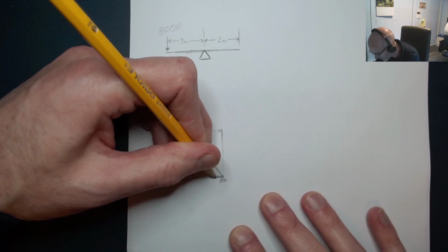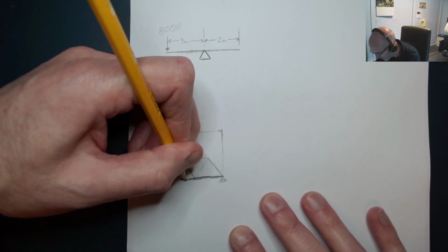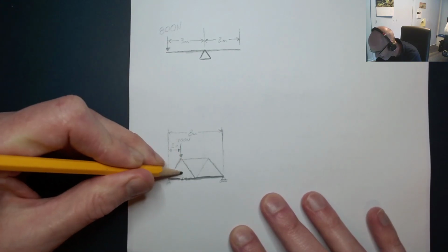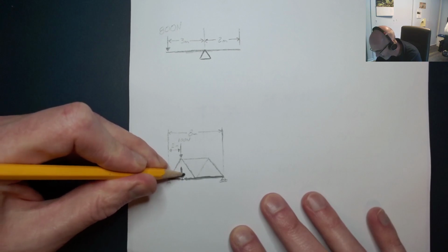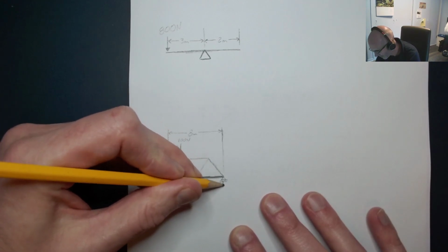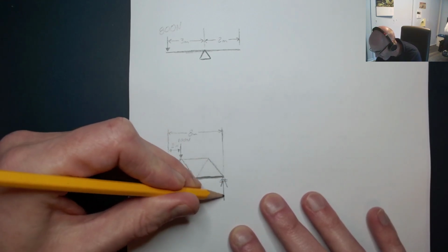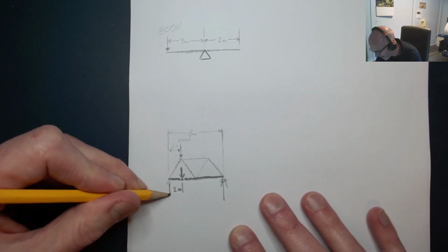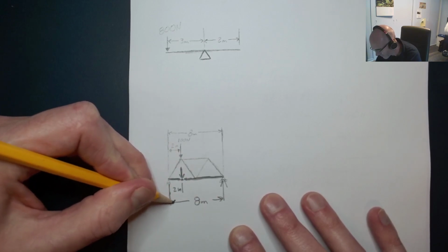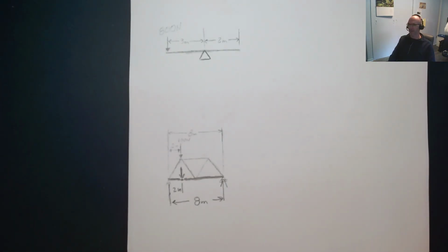And so what you're actually calculating now is that you've got a force of 100 newtons coming down here at a distance of 2 meters, and then it's being supported out here by a counteracting force coming up in this direction at a distance of 8 meters. This is actually going to be the first step in calculating the more complex stresses that we'll be getting to in a week or two in this course, but you may as well jump in right there.